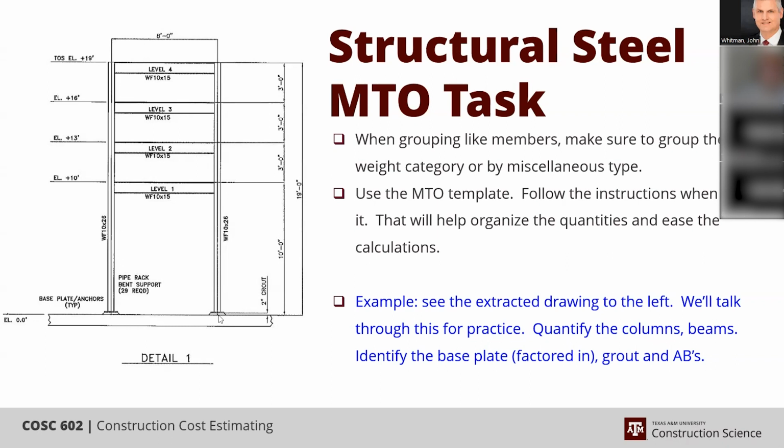In reality, if we were performing a regular project, I would have held off from quantifying the grout in the concrete like we did, and I would have quantified them here. The reason being is that here you have a better view of what your base plate sizing is. On that one, you have to assume, because it didn't talk about the base plate sizing. It just showed you where the anchor bolt pattern was going to be. And you would have had to have looked at the steel structure to find out what your base plate sizing